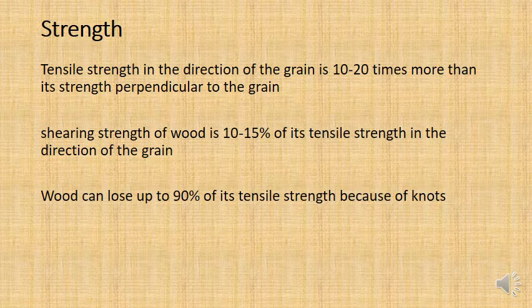But what you need to know is that the grains of the wood, basically the fibers, those wood cells, the strength will be considerably more if the loading is basically parallel with those grains.